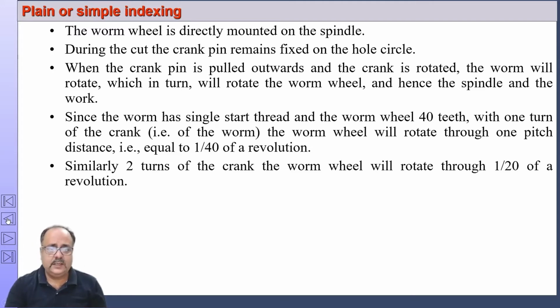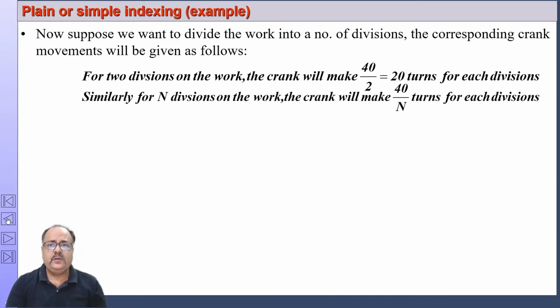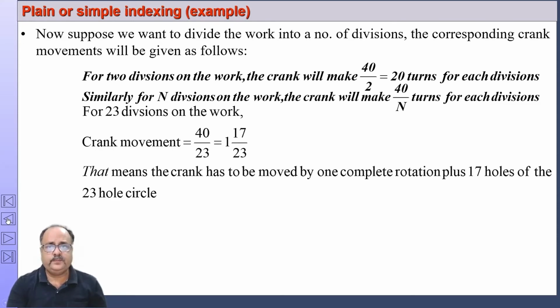Likewise, if I want to divide the workpiece into n number of divisions, the formula is 40 by n. For each division, we have to move the index crank 40 by n.